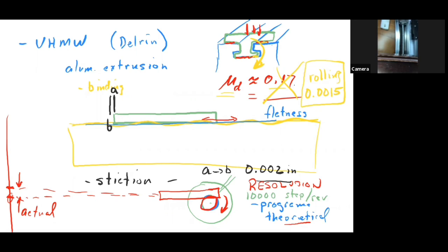And that's why we're going to use linear bearings, not linear bushings. But it's worthwhile to kind of go through, start at the bushing level, because you're always tempted to start there because they're so cheap and they're easy to make things move back and forth, especially with UHMW or Delrin, very common material. And we made you use it in 140 as your bearing. That was your bearing. And yeah, we're kind of in the back of the room going, yeah, this is really bad, but at least you could design something and you didn't know any better.